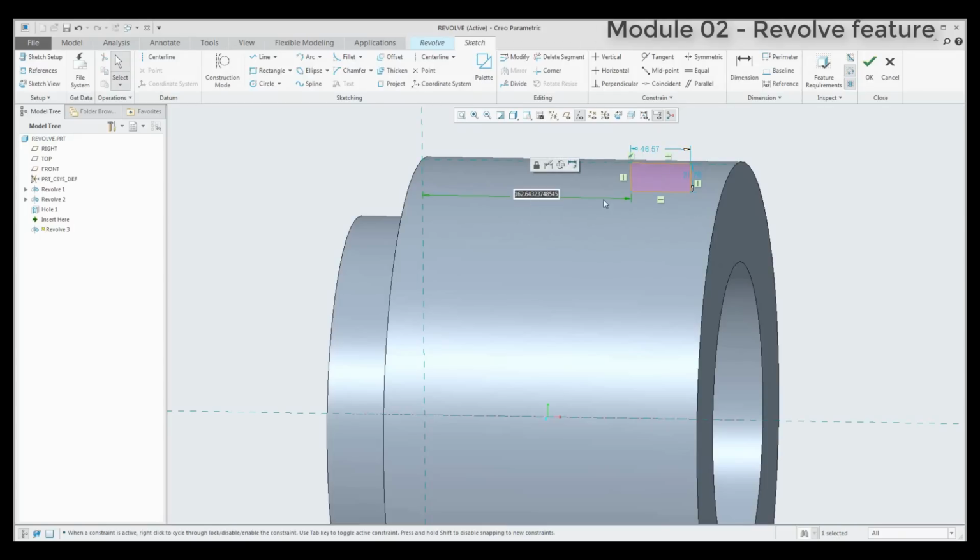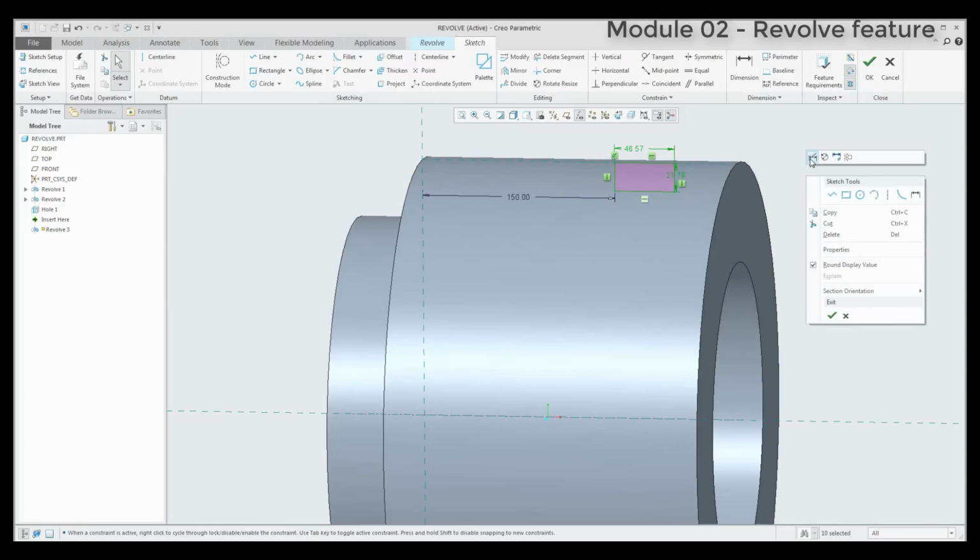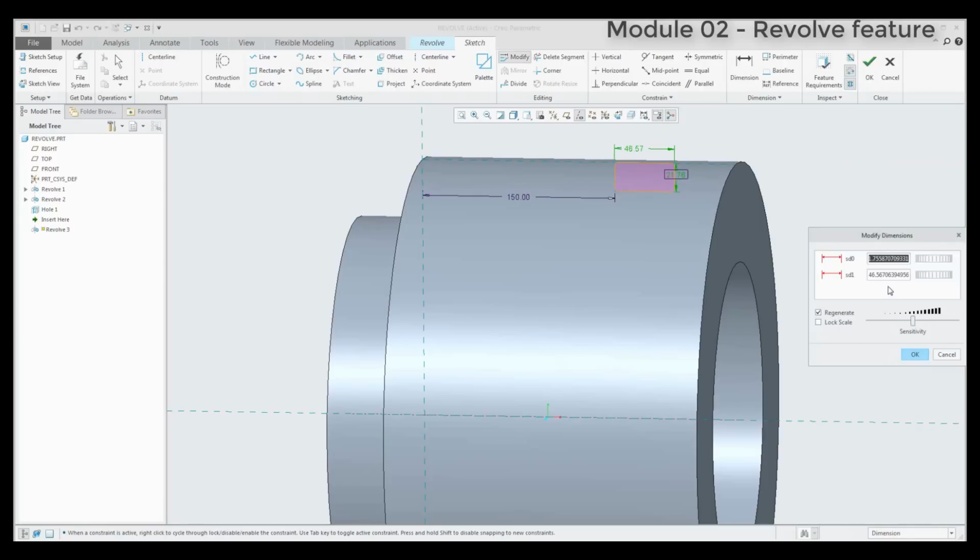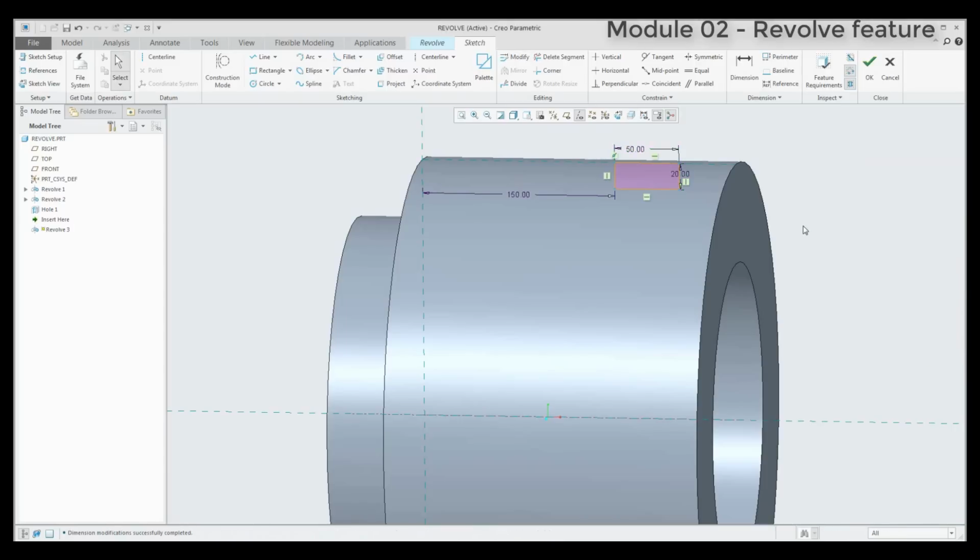You will specify the information or necessary dimensions, and you can change it again. So for example like this, or if you would like to modify more, you can use the right mouse button, and over there is the layout menu with the modify icon. And again, you can set the new numbers and confirm with enter from the keyboard directly here. So there are two options for how you can modify the dimension: directly by double click, or select the dimension and use right mouse button modify. Or over here you can see the modify